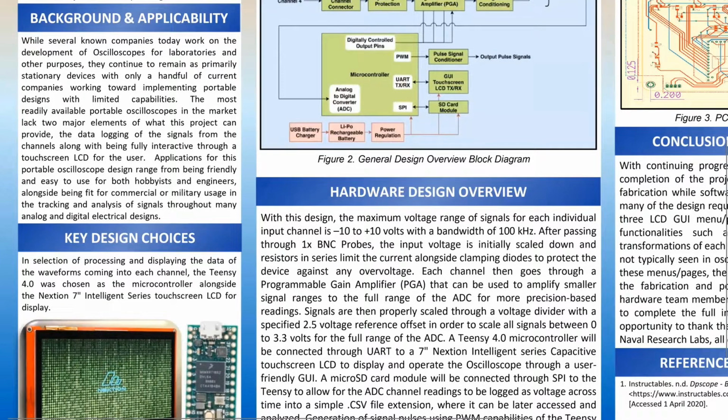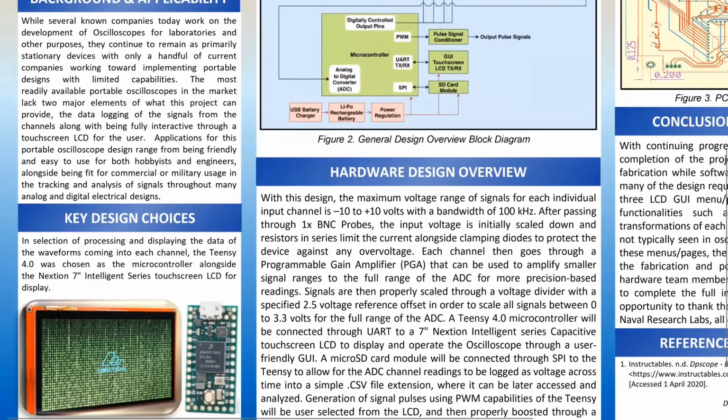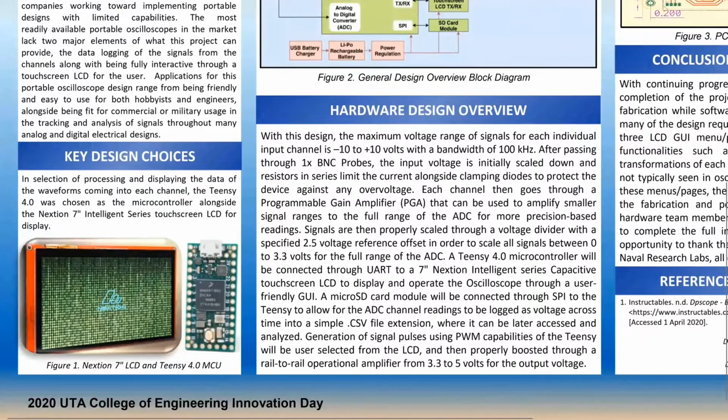Applications for this portable oscilloscope design range from being friendly and easy to use for both hobbyists and engineers, alongside being fit for commercial or military usage in the tracking and analysis of signals throughout many analog and digital electrical designs. In selection for processing and displaying the data of the waveforms coming into each channel, the Teensy 4.0 was chosen as a microcontroller, alongside the Nextion 7-inch Intelligent Series capacitive touchscreen LCD. Now, Bishoy is going to talk about the general design overview.